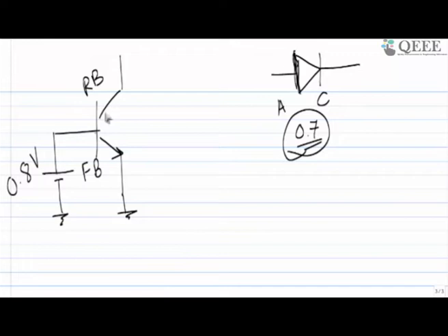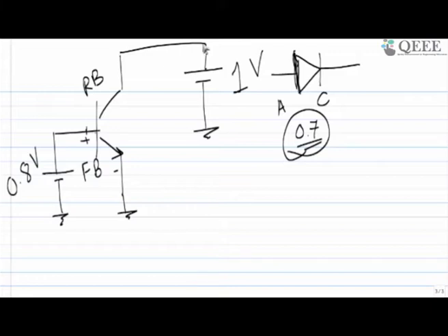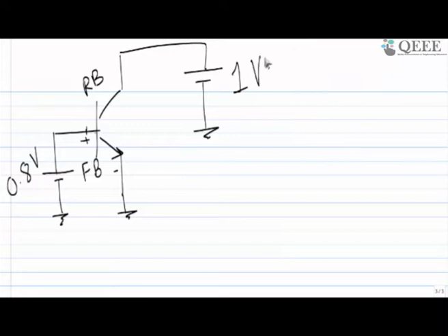And this side there is one more PN junction. This side has to be higher than the VBE or base to emitter voltage. How much am I going to apply? In this one they have applied 1 volt, if I am not wrong. Yes, so they have applied 1 volt, and this side is reverse bias, and this side is forward bias. Now what is happening? So let's draw the equivalent